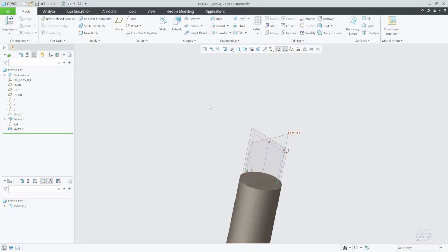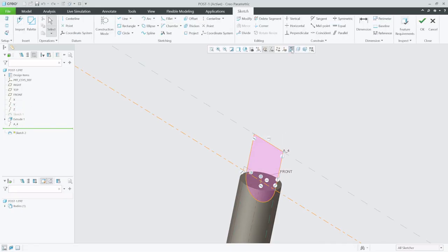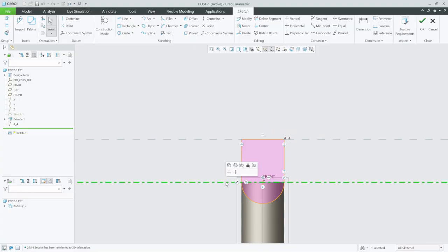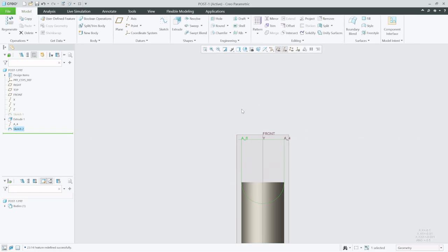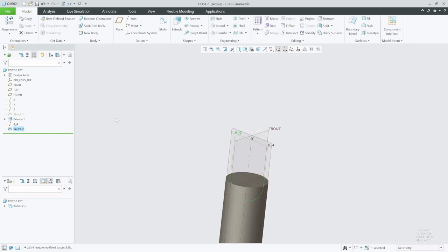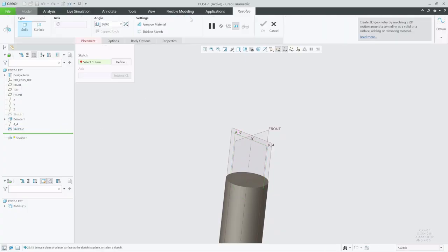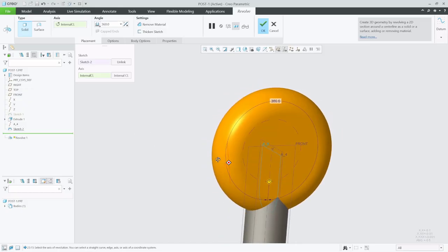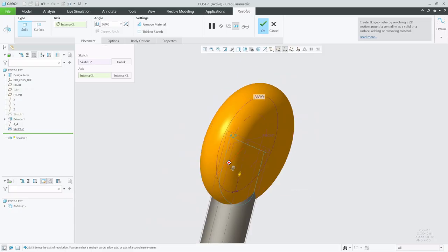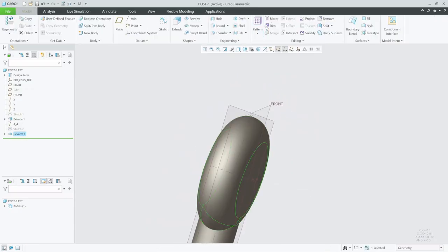You know what the problem is? We need to add a center line here. So let's take this out to add a center line here, because that's the problem. The revolve's not going to work with the center line in the wrong place. So now if I've selected this, we're going to say revolve. Select that sketch. Okay. As you can see, 360. Cool. And say okay.